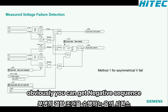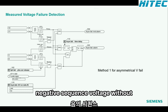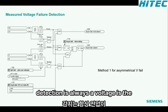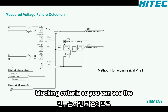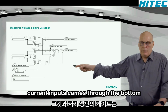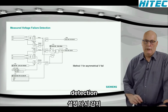Obviously, you can get negative sequence voltage during fault conditions, but in a power system, you cannot get negative sequence voltage without negative sequence current. So in the classic fuse failure or measured voltage failure detection, the voltage is always the pickup criterion and the current is the blocking criterion. You can see the presence of negative sequence current, I2, further down will go in and be the blocking input. The current inputs come through the bottom, and at that AND gate at the top, it's a negated input at the bottom. It's where the current comes in and will block the fuse failure detection.